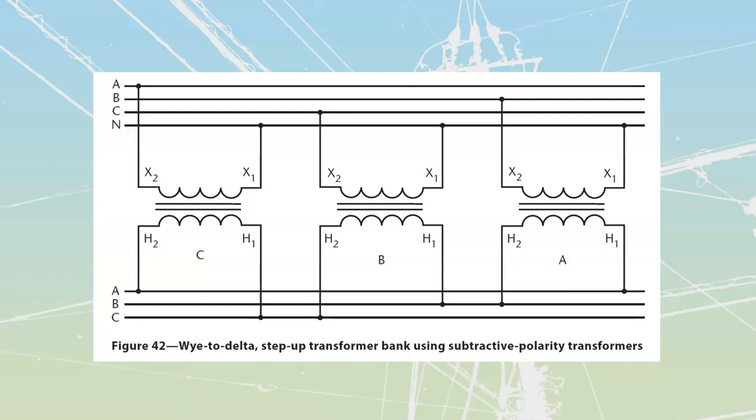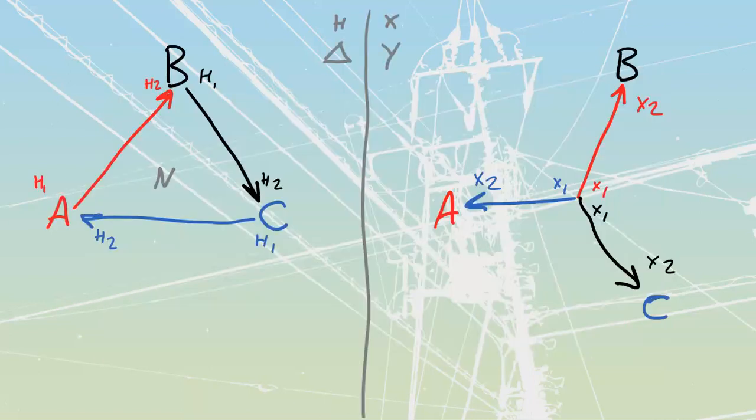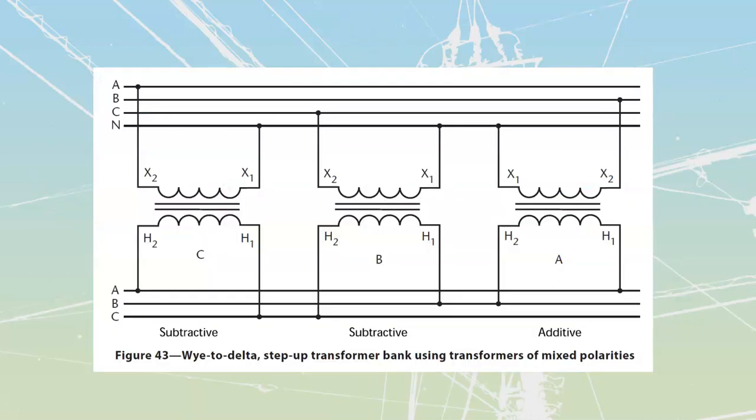Note once again that my A, B, and C are all the way across off of these ones here. Subtractive values of transformers are being placed across here. But once again, going through that same setup that we have, it's going to be the exact same layout that we are going to be following, where we're going to have X1s tied together onto a neutral.